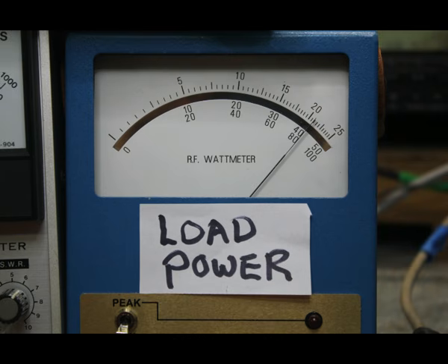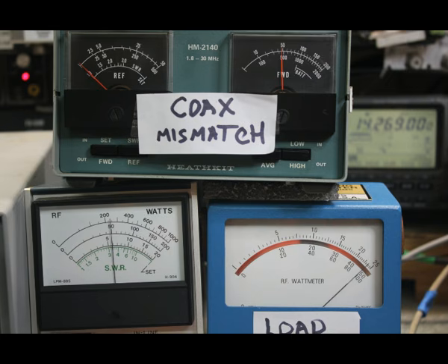So at the load end of this setup, we now know that we have around 42 or 43 watts of power delivered when that coax is running at a 10-to-1 standing wave ratio. That really flies in the face of all these tables that tell you that you should have significant power loss in the cable from a 10-to-1 standing wave ratio. If you remember right, when we started out, we were at around 47 watts at the load. So we've gone from 47 watts at the load to maybe 42 or 43 watts because of having a 10-to-1 standing wave ratio on that 25 feet of LMR 400 cable.